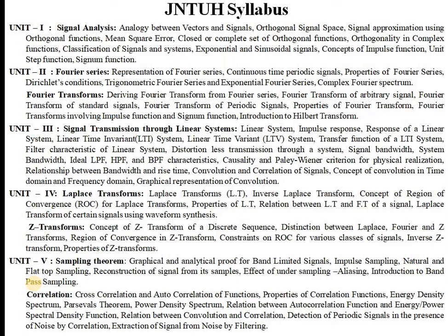And also we will study a mathematical tool for knowing about different kinds of similarities between signals, which is what we call correlation. We will be studying autocorrelation and cross correlation. If we would like to know the similarity with respect to the same signal, we generally call it autocorrelation, and if you would like to find the similarity between two different signals, we generally call it cross correlation.